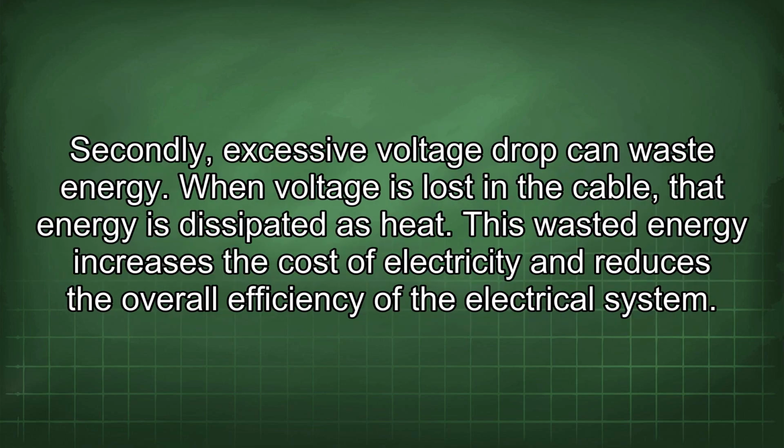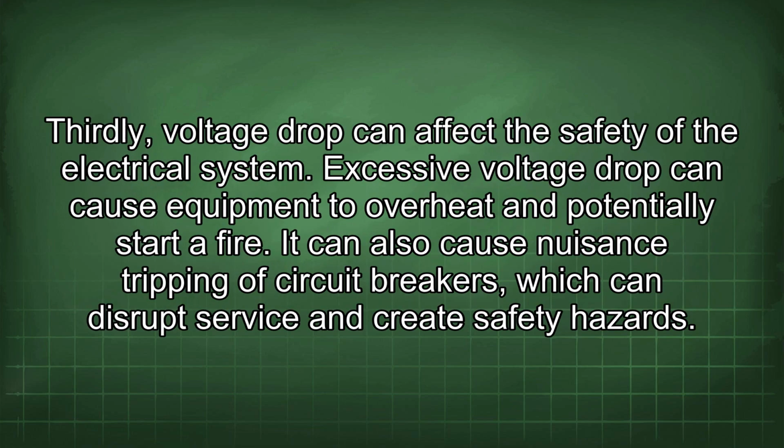Secondly, excessive voltage drop can waste energy. When voltage is lost in the cable, that energy is dissipated as heat. This wasted energy increases the cost of electricity and reduces the overall efficiency of the electrical system. Thirdly, voltage drop can affect the safety of the electrical system.